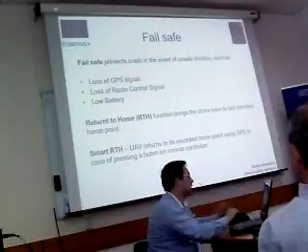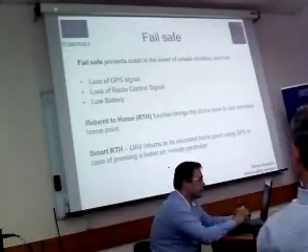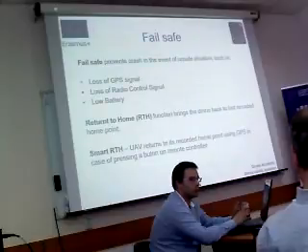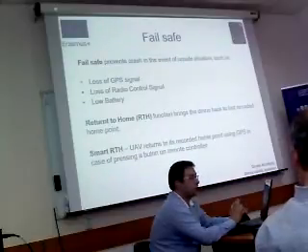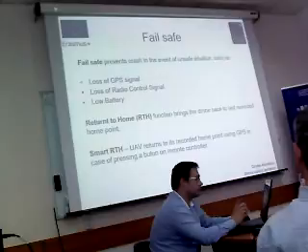The next safety system could be failsafe. Failsafe is a special stage where the drone is considered to be without control, so the control link between the radio and receiver is off. It is a set of instructions that the flight controller will execute in case the control link has failed.